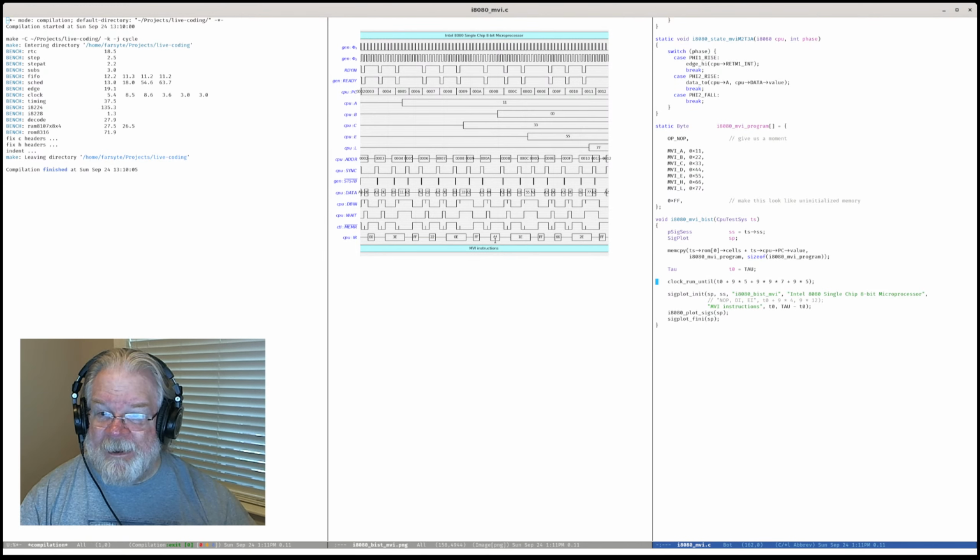So here's the execution of just the NOP instruction. So we get PC goes from 2 to 3. Address 2 sees the NOP, NOP into IR, and we get to address 3 here.